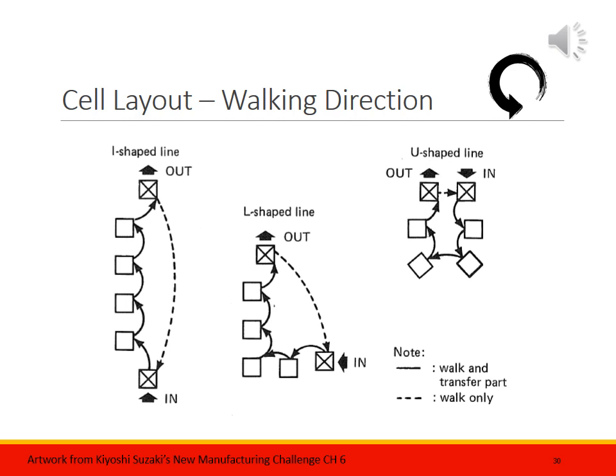As the takt time, the demand, we talked about takt time, as the takt time increases, follow me on this, right? When takt time increases, that means you have more time between parts, or more time to make the parts, because the demand has dropped. So as the takt time goes up, which means demand goes down, you want to be able to match the cycle time to the takt time. We said that a couple weeks ago, right? So how do you match the cycle time with the takt time?